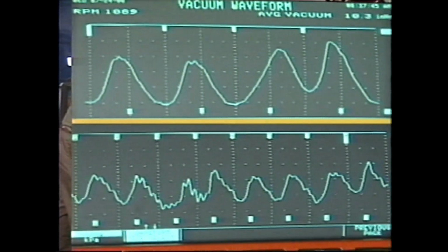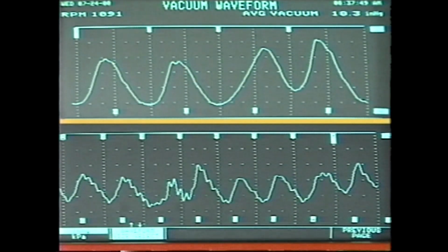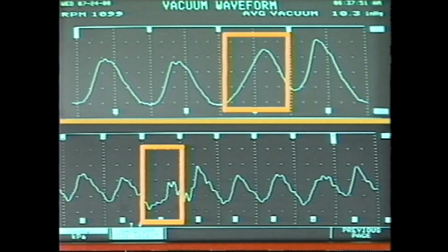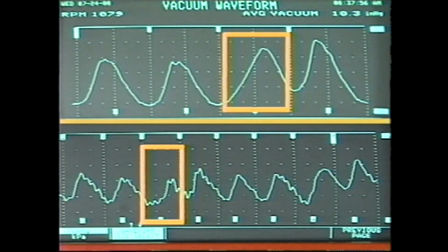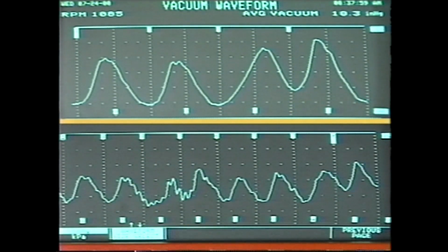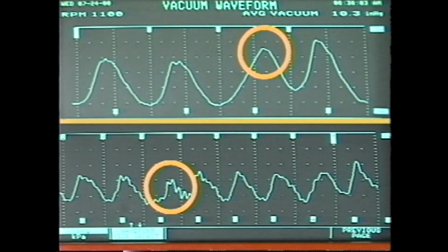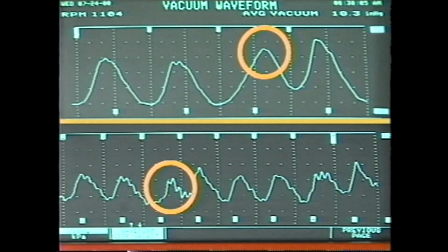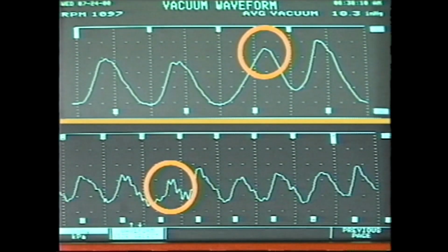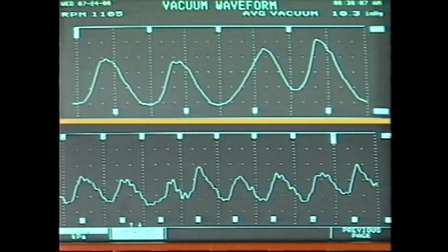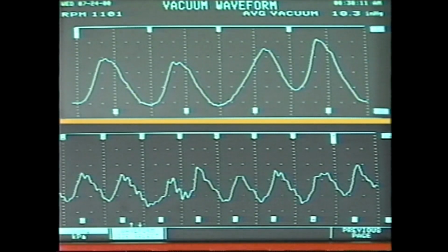Let's compare the abnormal test patterns from a 4-cylinder engine and a V8 engine. Look for a problem in cylinder number 1 of the 4-cylinder engine and cylinder number 7 of the V8 engine. Mechanical problems that affect the intake valve opening will show up in the waveform as a delayed peak if the timing is off, or a shorter descending slope depending on how much the opening is restricted. If a lot of vacuum is lost, the pattern for the adjacent cylinder may be affected.